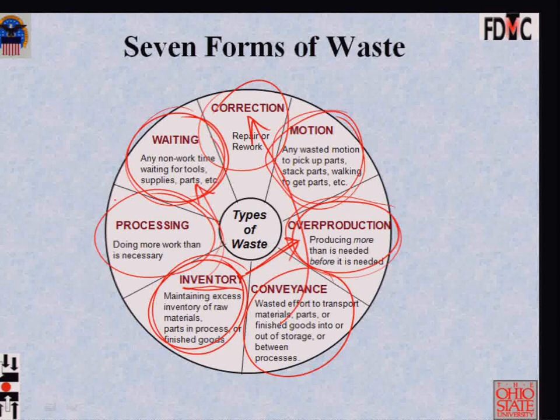We tend to think that every operation is value adding. But many times the question is, are you using too many operations? In which case some operations are waste. Then are certain operations very time consuming? Are certain operations causing excessive tool breakage or material spoilage? So many times what we think is a value adding step, processing, is actually potentially non-value adding.